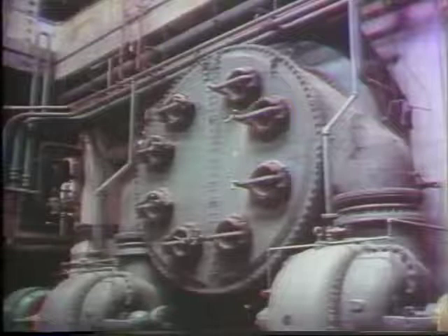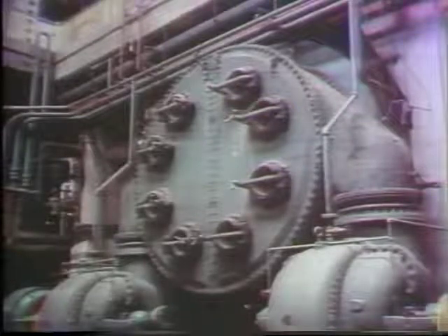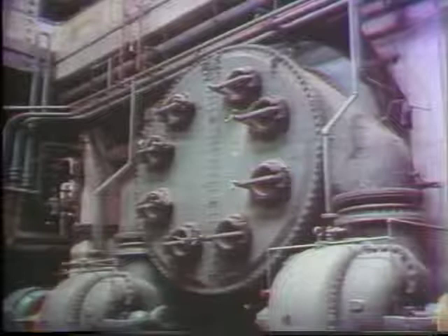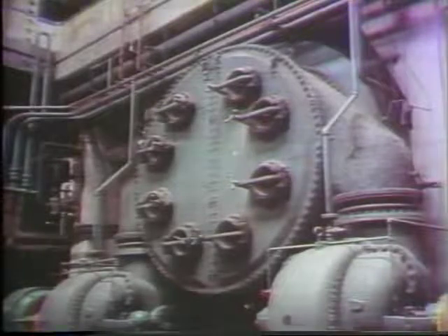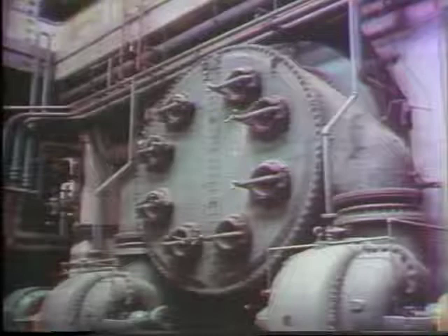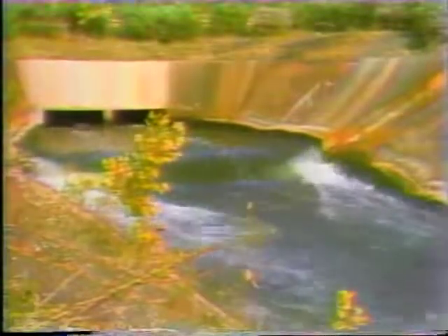Another major source of potential pollution is the condenser. The major job of the condenser is to remove heat from steam. So what we're concerned with is thermal pollution. Depending on the type of water cooling system, heat is released directly from the plant into lakes, oceans, rivers, or into the air through cooling towers. Heat released into a lake, ocean, or river can raise the water temperature. If the temperature gets high enough, it can affect animal or plant life in the area.